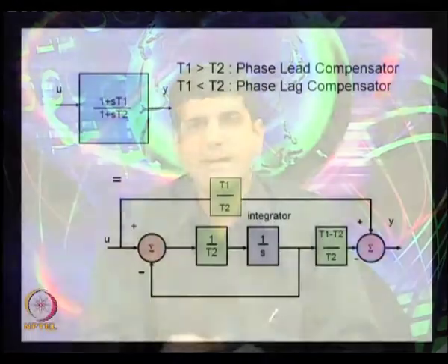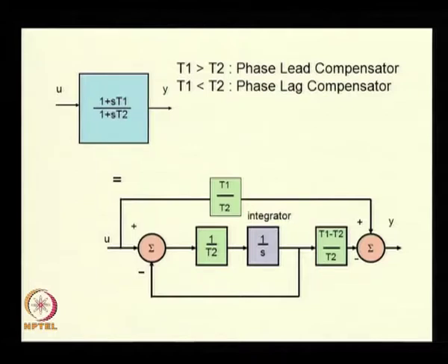A multiplier is a nonlinear block. So, you can't form an integrated transfer function in case you have multiplier blocks anywhere. Here you do not have multiplier blocks in the 3 transfer functions which I have shown you here. They have only summers, gains and integrators. But you could have, under certain circumstances, limiters and multipliers coming into the block diagram which make your system non-linear.